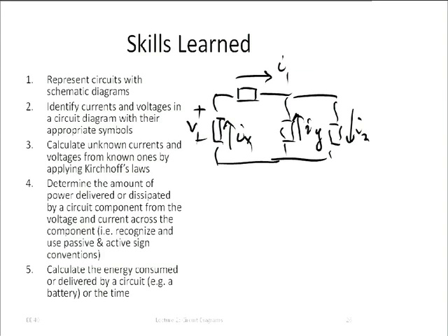Right, so now we really have to use Kirchhoff's current law. We would, for example, sum all the currents that are leaving this bluish shape here. So that would be minus I1 plus I2 minus Iy equals 0. Okay, and then you can solve for Iy. Why does it have a few minus signs? Exactly. Hey, please, not always. Although, in fact, I would like answers from the back, right? So these currents are actually entering the node; they're not leaving the node. So we need to put this minus sign.